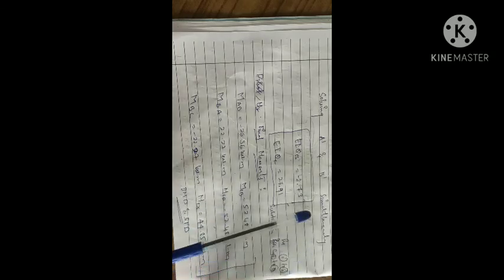The procedure for drawing the BMD is to draw the free BMD, which is the moment at the center span and end spans, and then apply the final end moments. We will discuss that in the live class. Only the drawing part is remaining, since we have all the values. Okay, thank you.